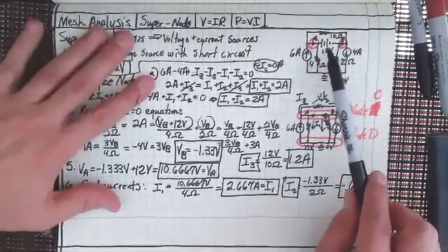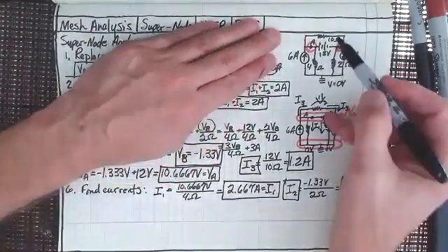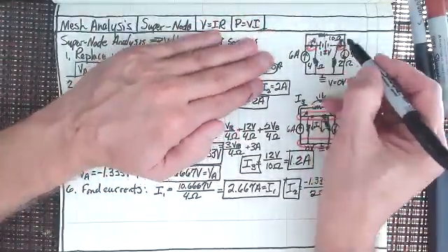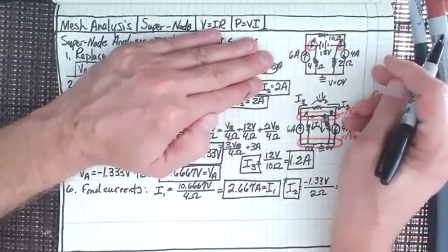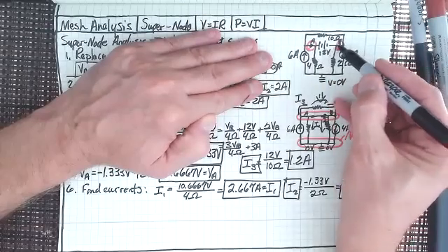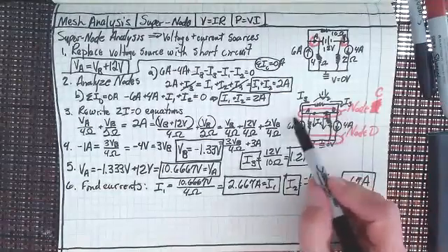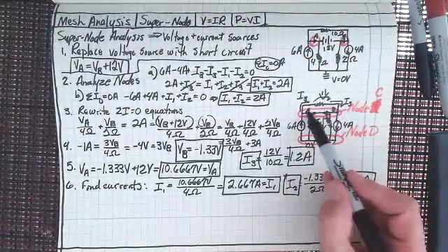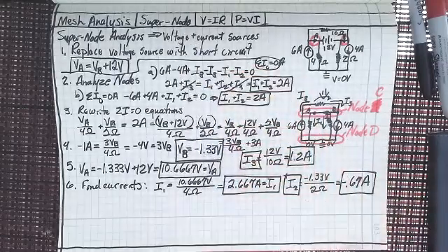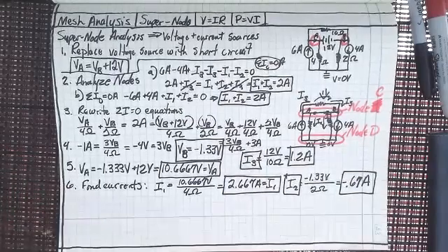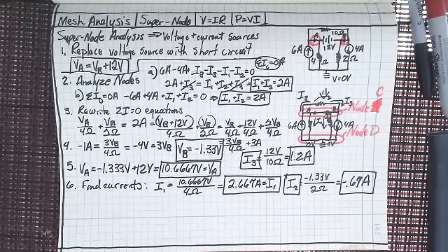and you can see how, when I go back to the original circuit that I've got here, I now know everything about that circuit. I know what the current flowing through the 10 ohm resistor or the 4 ohm or the 2 ohm resistor is. I know what my voltages at A and my voltages at B are because I've replaced that and used this as a common node, but I've always kept that analysis between that difference between the two, and I've included that in the analysis that I've done here. So I think everybody can see that supernode analysis gives us the ability to figure out what the currents and voltages are throughout the entire circuit if I have a mixture of current sources and voltage sources. All right. I hope that's pretty clear.